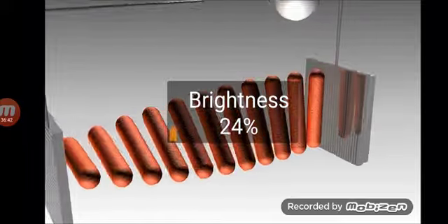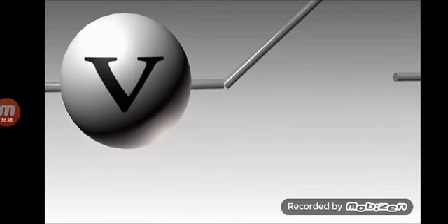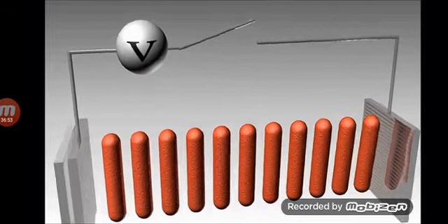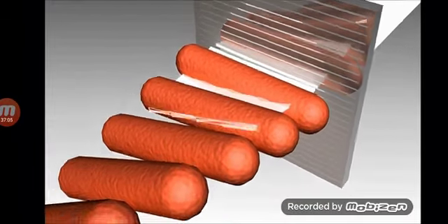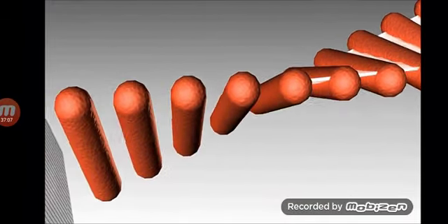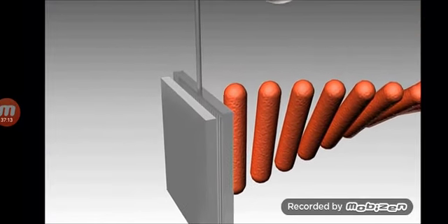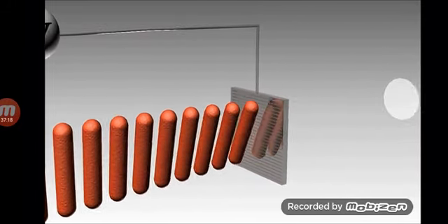This is the liquid crystal material I was talking about. This side it is horizontally polarized, this side the glass is vertically polarized, and this is the liquid crystal material in between. Here you can see the earlier orientation, and this is the new orientation. When we give certain energy, this is the light source. When light enters through the horizontal plane, just because the orientation of the crystal has changed, the same light can pass through to the output side of the chamber. So the light that entered is available at the output side.